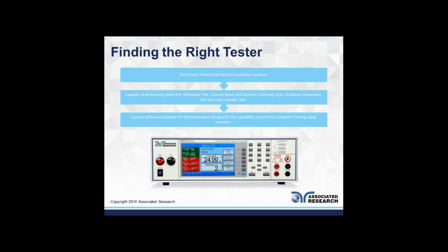There are some standards that require 15,000 volts being applied. This applies to different categories of DUTs, but some of the commonly known high-pot testers can only output up to 5,000 volts. So you want to look at where your DUT falls, what category according to that standard, find out what voltage it needs to be tested at, and make sure the tester is able to perform that.